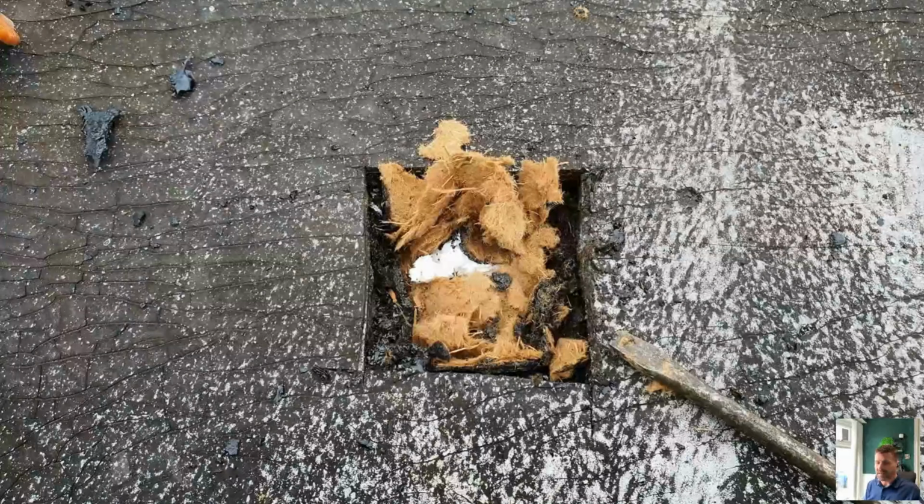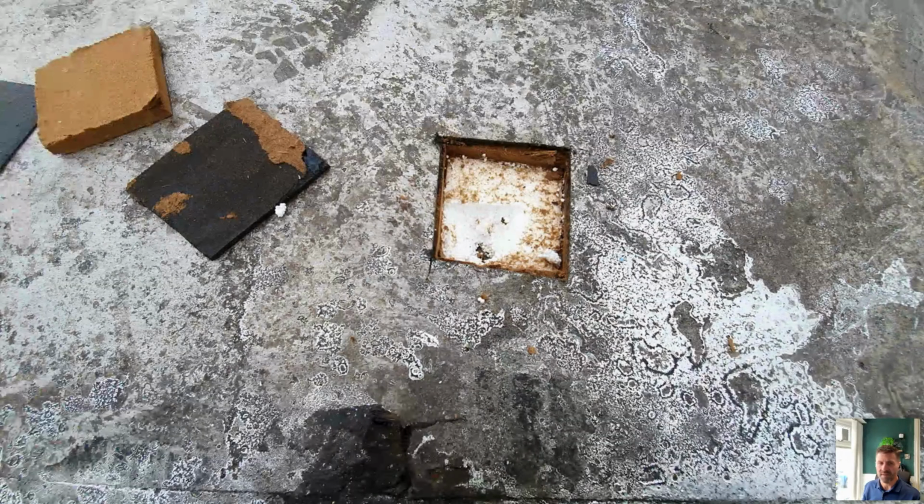Obviously, polystyrene melts if you put anything hot on it, so the fiber board was bonded to the top of it so that the felt could either be torched onto it or pour and roll onto the top of the surface without damaging the polystyrene underneath. So you might find a fiber board which is 13 millimeters thick, and then your polystyrene underneath. So again, fiber board, polystyrene composite in that instance.